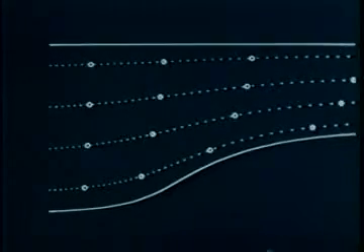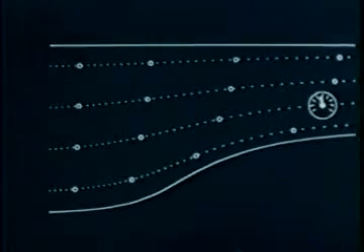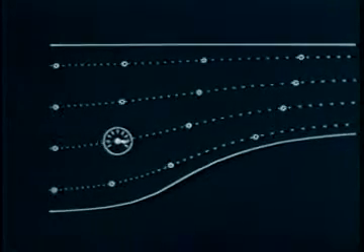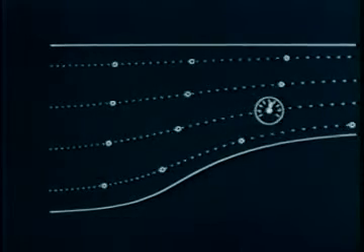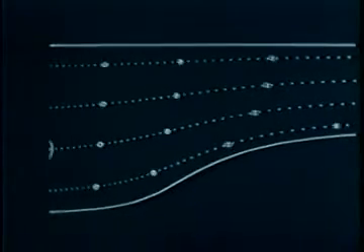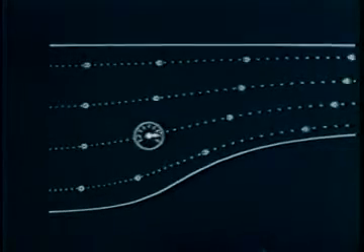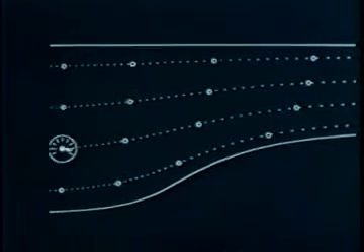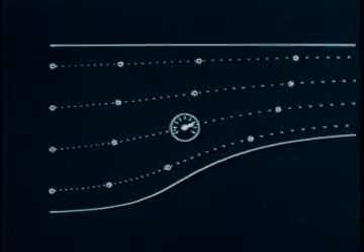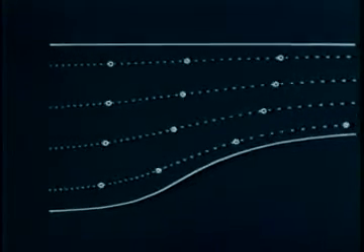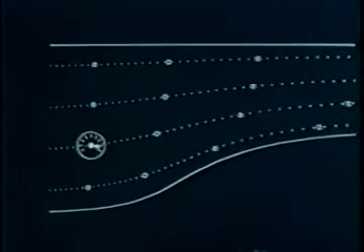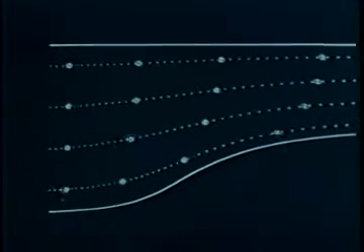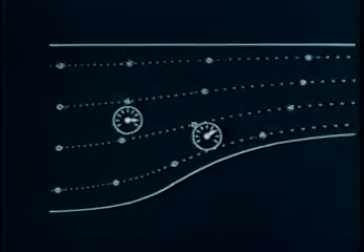We can imagine attaching an instrument, like a pressure gauge, to a moving point, to make what we might call a Lagrangian measurement. This sort of thing is attempted in the atmosphere with balloons of neutral buoyancy. If the balloon does indeed move faithfully with the air, it gives the Lagrangian displacement. Such Lagrangian measurements are actually very difficult, particularly in the laboratory. We usually prefer to make measurements at points fixed in laboratory coordinates.